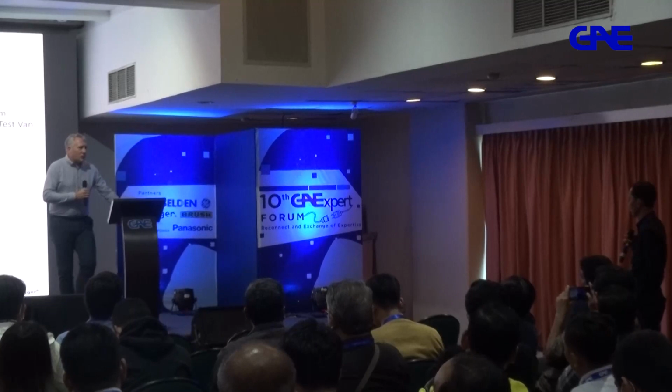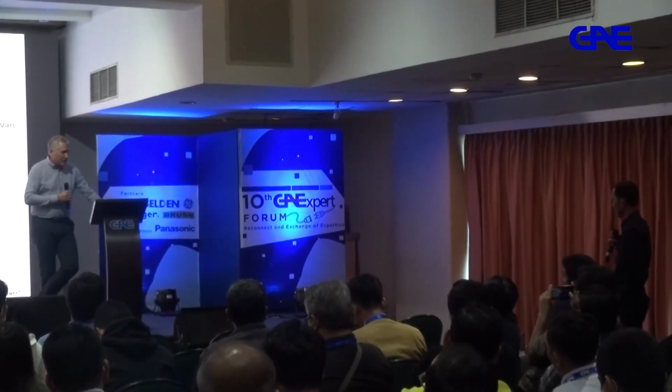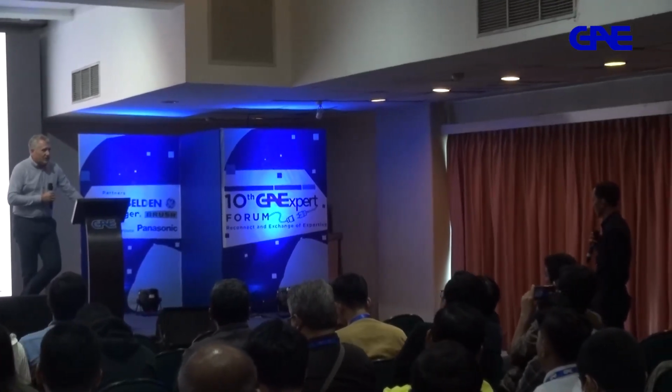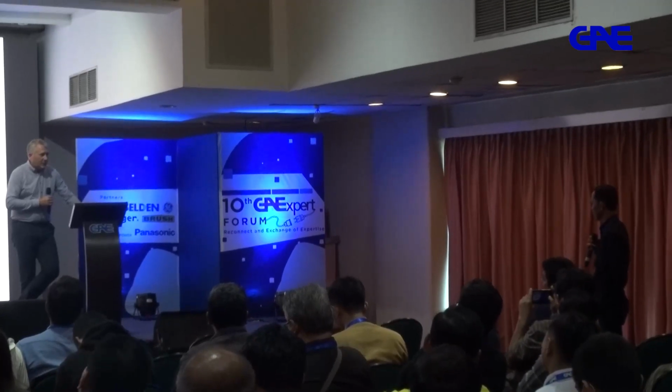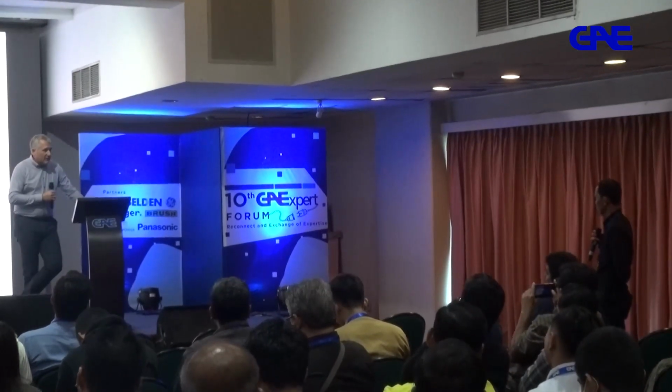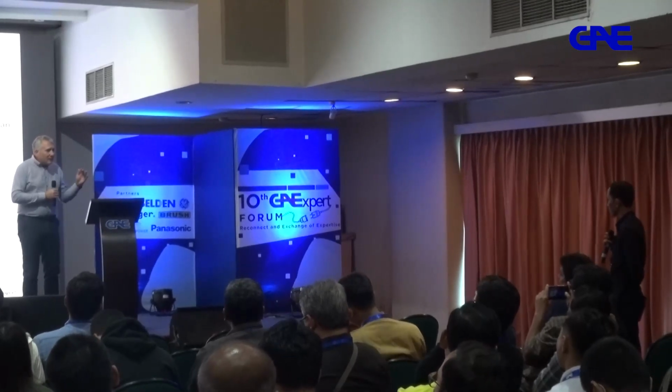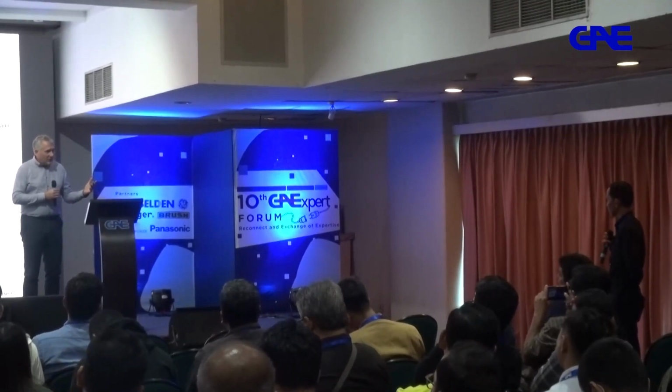It depends very much on your asset. I'll give you examples. Certain assets like GIS, GIL should not have any PD. Motors or generators, by definition, have a certain level of PD. So you need to understand very well the asset you're dealing with.